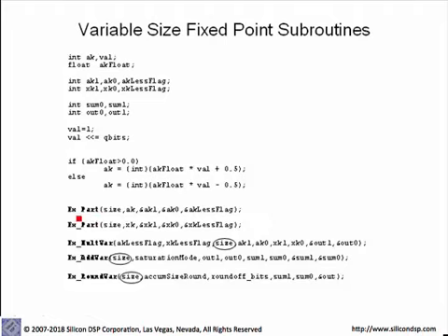For example, the fx underscore part routine, which takes a 32-bit integer as input and depending on the specification of the size breaks that up into multiple parts, and these are used in the actual variable precision multiplication in order to do the modeling for a variable precision multiply with register sizes, for example, from 8 by 8, 16 by 16 to 32 by 32 type multiplications.